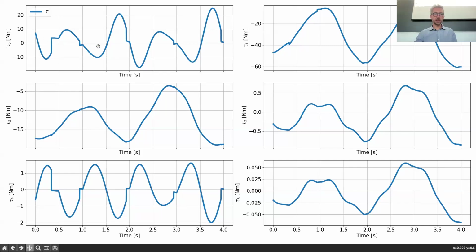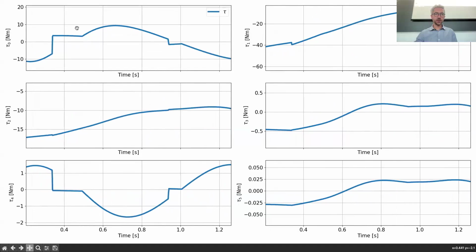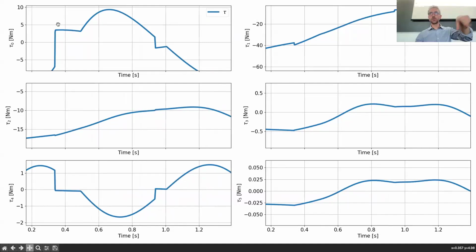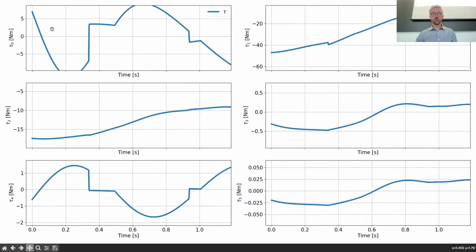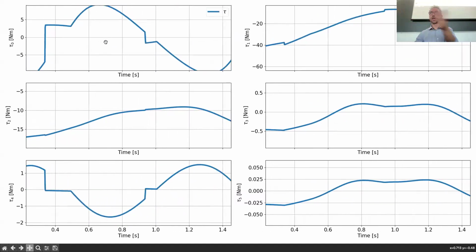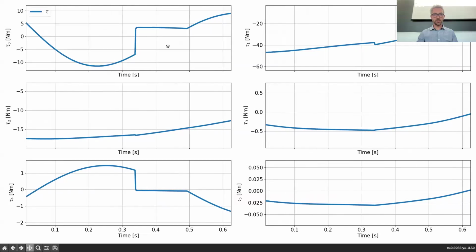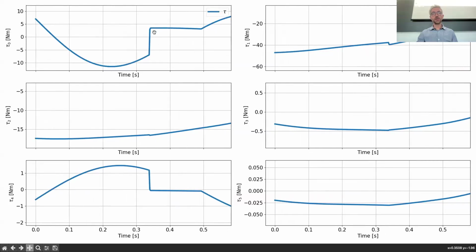Inside the plots, you can zoom things in all directions. When you zoom the time axis, it scales the time axis on the 6 of them, which is, I think, a nice feature. So when you move, you see horizontally, they're all aligned. So the time axis is actually shared between the 6 plots. And we can see indeed that there are some moments like this one, for instance, where we have a discontinuity in the joint torques. So we're going from -7 to +3, roughly.